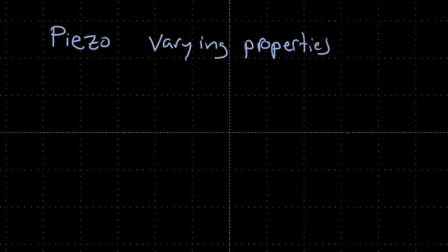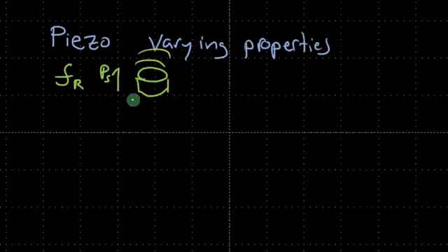So upon further inspection, he was describing what we know as the resonance frequency. And for this application, he had discs, and he's talking about the resonance in the 3-3 direction. So the poling direction is like this, and the resonance vibration is in the 3 direction. So longitudinally, that's the vibration. Not longitudinally, in the thickness. He used my videos about how to measure the resonance frequency.